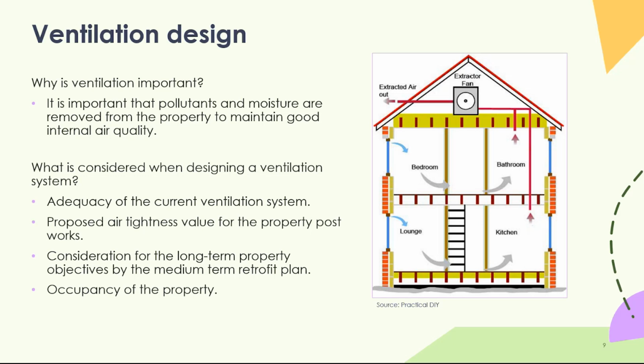So you'd have to look at the initial starting setup with the ventilation, and think about how the building's currently performing, how what you're doing to it, particularly doing fabric works, might change that, and therefore what the air tightness of that building would be afterwards, how you can maintain, or in many cases improve upon the ventilation of that property, so that you avoid all those things we just talked about in the previous slide.